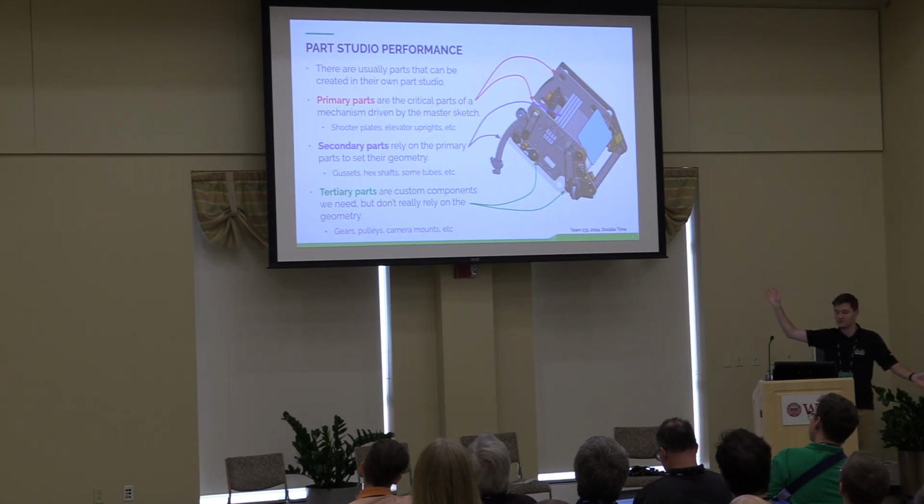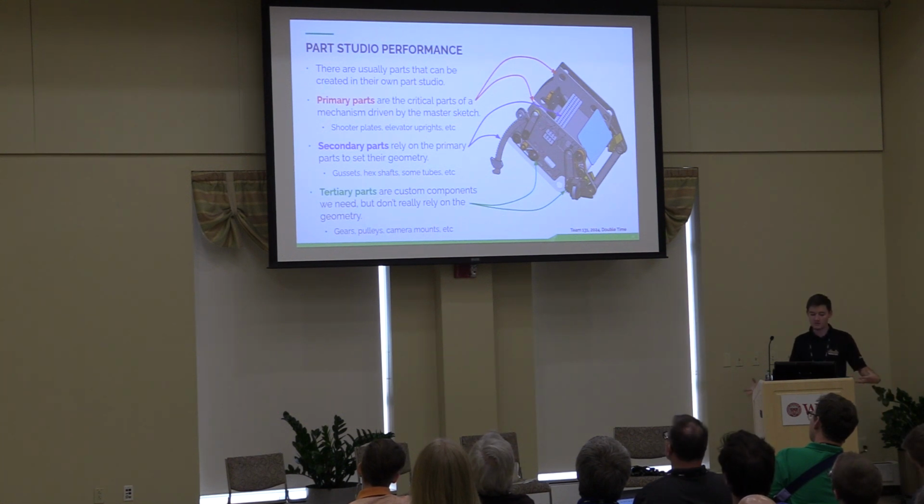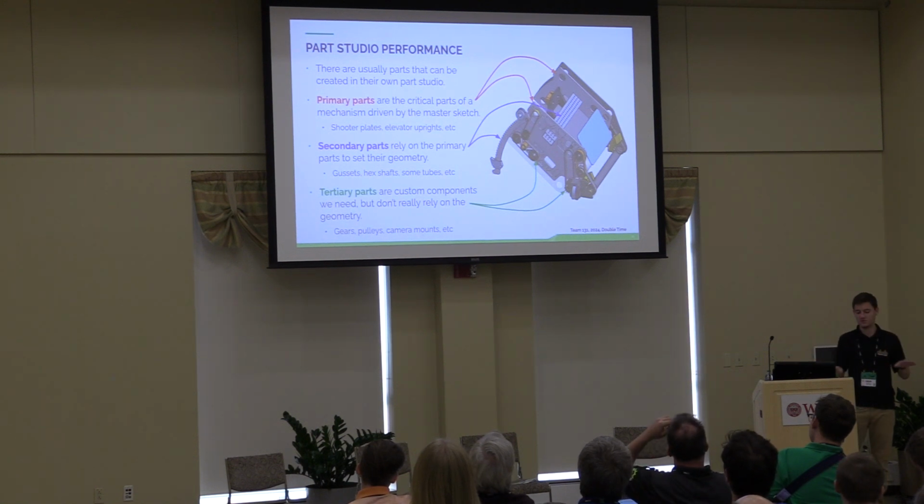Of course, it's something I came up with for this presentation. You can take it or leave it, but I do think it does a good job of explaining what is going on and how to break it down. So there are usually parts that you don't need to have in the same part studio. It's nice if there's one part studio for the whole sub-assembly, that's great. Sometimes you just don't need to.